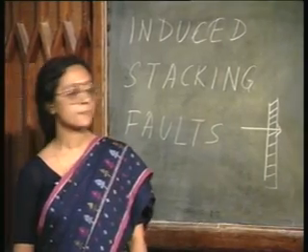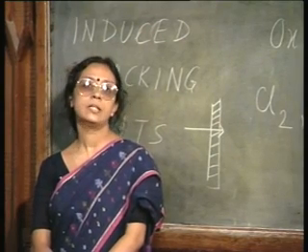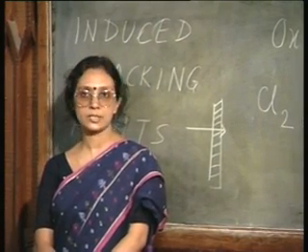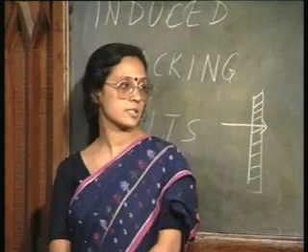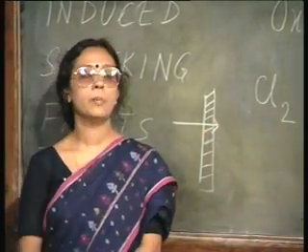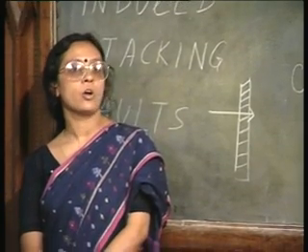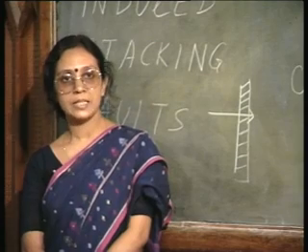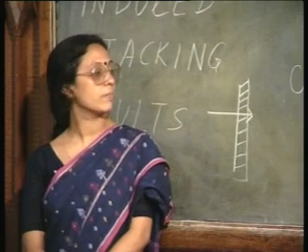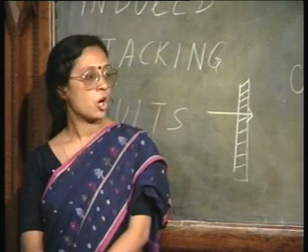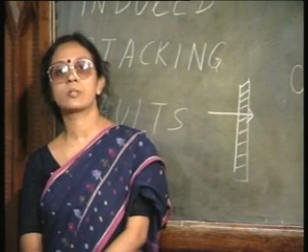Therefore, in a practical case, at the end of the oxidation, it is found that at the silicon-silicon dioxide interface there will be a large number of silicon interstitials. Now, at least a small fraction of these silicon interstitials will move into the bulk of the silicon crystal. In the bulk of the silicon crystal, there may already be some defect sites present. These defects might have arisen at the time of crystal growth itself, or because of some mechanical damage on the surface, or, if an epitaxy was being performed prior to oxidation, because of some growth hillocks.